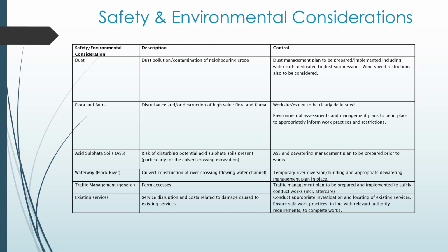Acid sulfate soils is a potential risk, may or may not, but worth having an acid sulfate soil and dewatering management plan in place just in case, particularly the area of the culvert crossing where there'll be excavation into the low-lying subgrade materials.